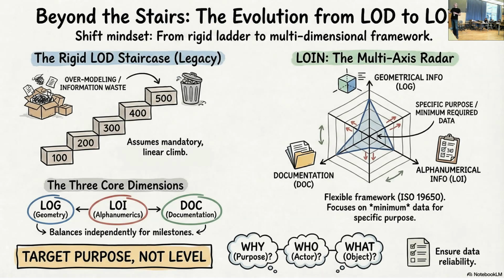Like, 100, 200, 300, but when do we need it? Why do we need it? The mechanical engineer only wants to know the amount of air in the room and the number of people in the room. Okay? And also the mechanical engineer wants to know where the building is situated and where you have windows. Okay? Rough definitions of windows. And who needs it? The mechanical engineer needs that information. Okay, from whom? The architect. What do they need? That's information about the space. So why? So that they can make calculations and see how much heating energy they need to pump into the space in the winter.